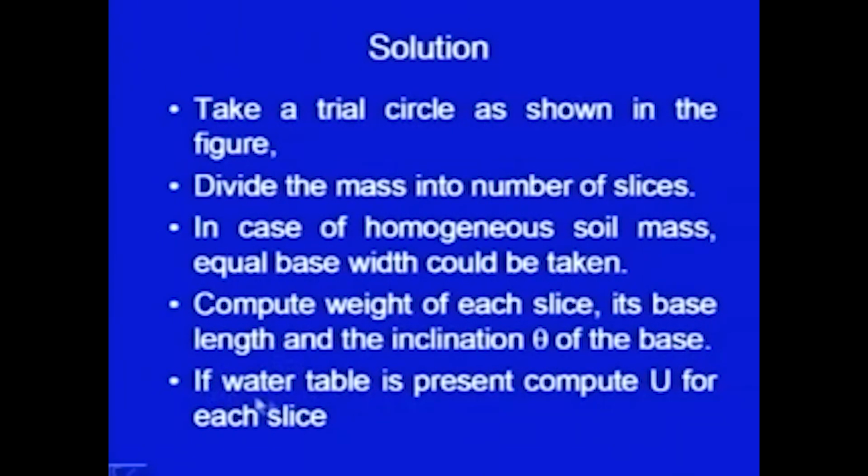And also, if water table is present, then compute U. Capital U is the force or total pressure. It will be small u into L. Small u you can find out from the flow net, and then you can multiply it with the base length and you can get capital U.